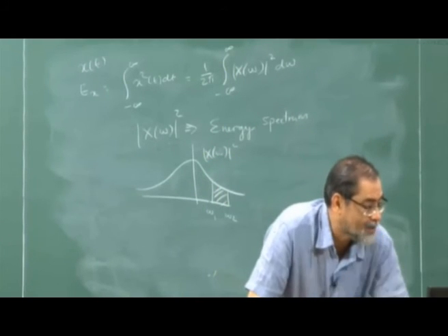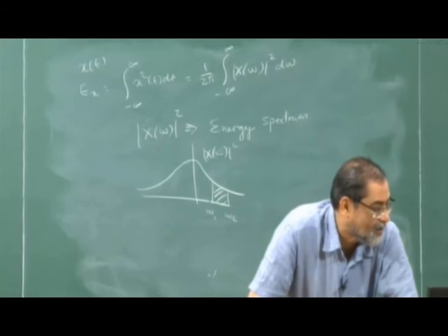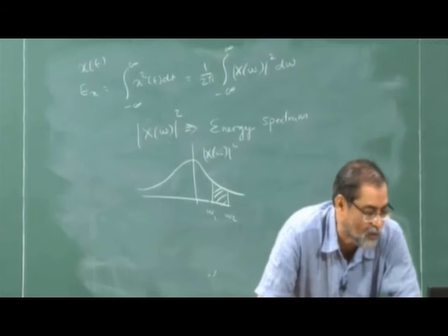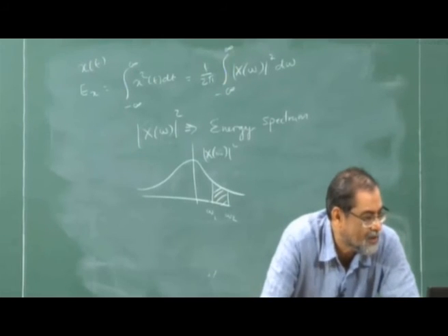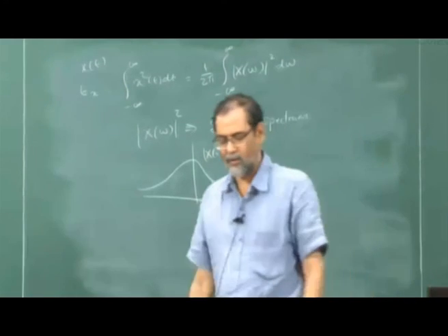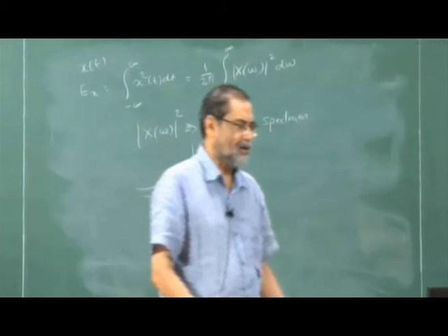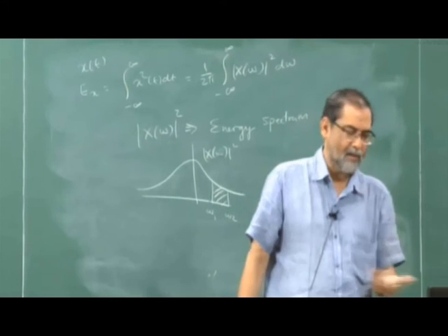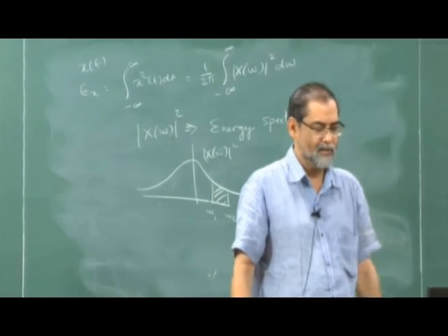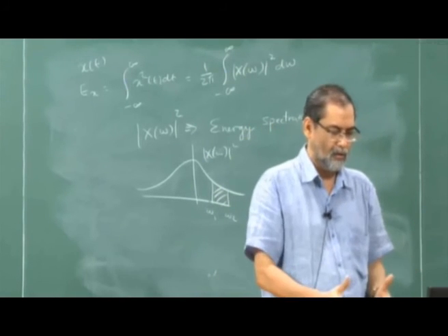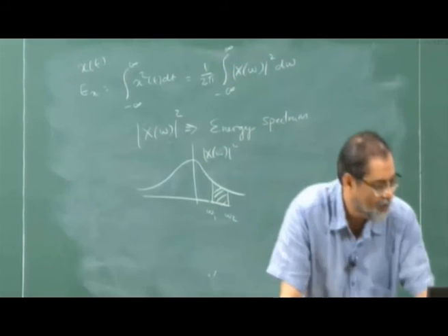If two systems are cascaded, then their impulse responses are convolved. Why? We talked about this a long time ago, when we talked about cascading of two systems. What is the physical significance of the power spectral density function? It gives you a way of knowing how the energy is distributed across multiple frequencies. It tells you whether the energy is in the low frequencies or in the high frequencies and so on.